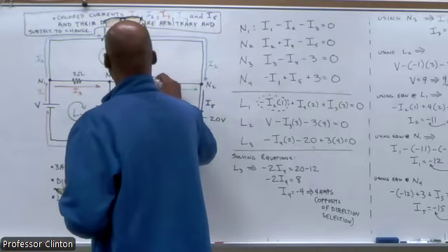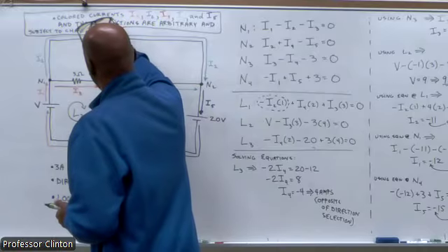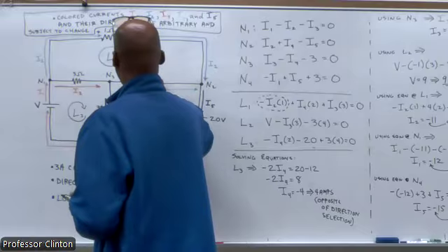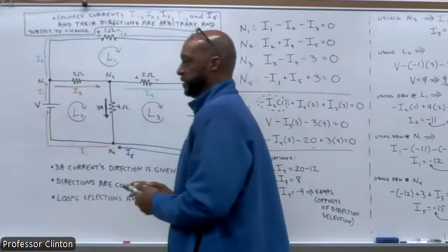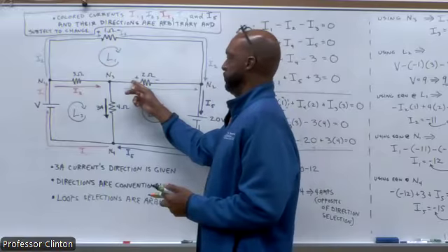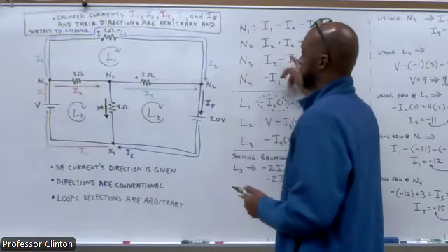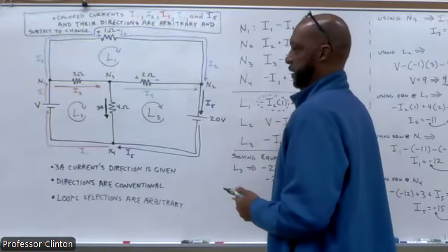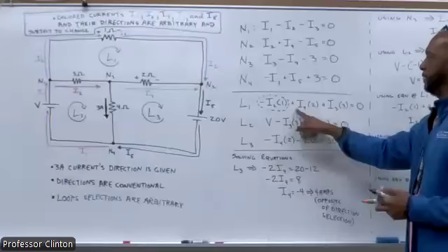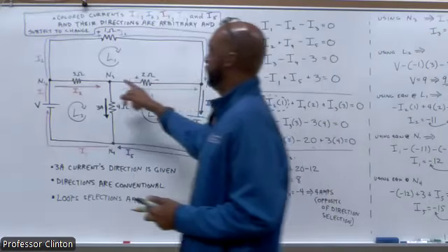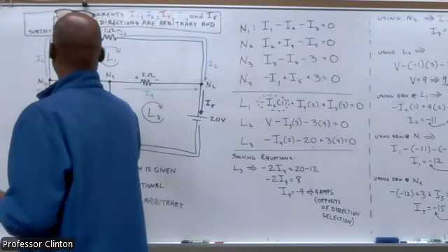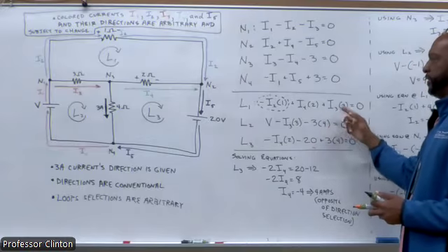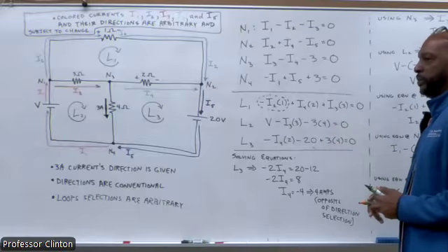So we're going to go from, let's see, over here, we went from positive to negative. This time we're going to go from negative to positive. So there's an increase of the voltage in this direction. So that's where in loop 1, we get this plus sign here, right? And then continuing through the loop, there's another increase of voltage according to my scenario, and we get that equation.